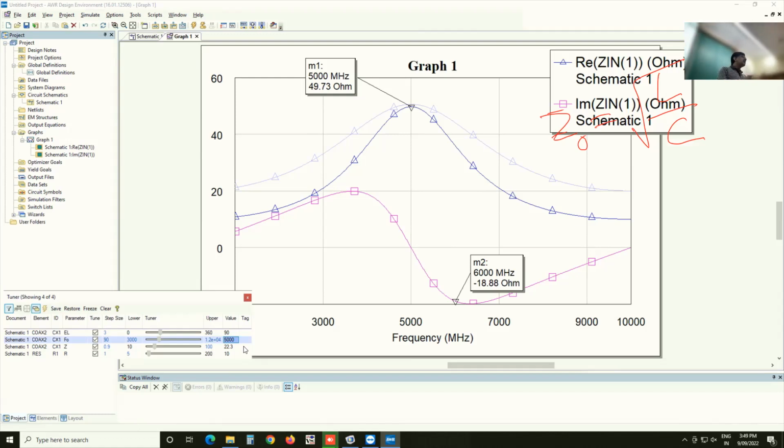Now you can take a limiting case of this and imagine a smooth variation in the L per unit length and C per unit length, so that the transmission line characteristic impedance itself is changing. Then there are questions like how quickly it can change. What does quickly mean? Over what length? When it comes to multiple sections of quarter wave transformer, the length is fixed. It has to be quarter wave at that frequency.